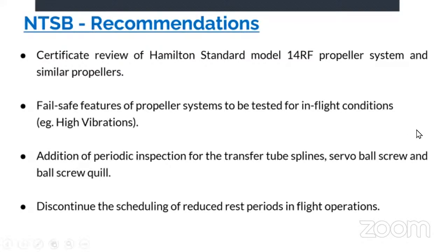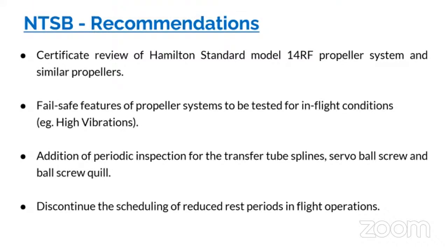in the flight. The transfer tube is supplying the servo ball and other propeller control unit parts, which were supposed to handle low torque and are made of cast material, which is supposed to be very reliable. Hence, periodic inspection was not included originally. However, NTSB included a servicing check at 900 flight hours after this accident. A recent change in reduction of rest period of pilots was also removed for ASA.